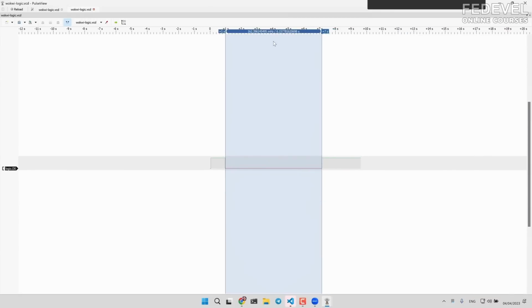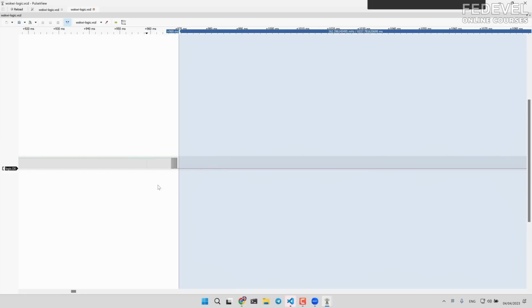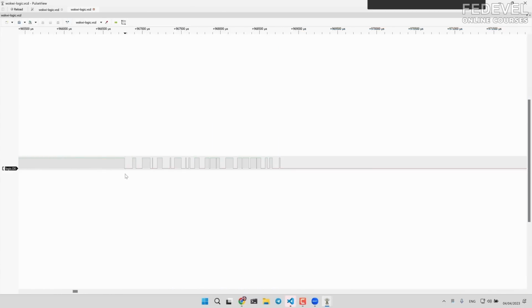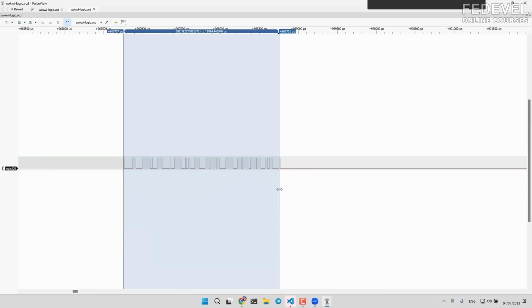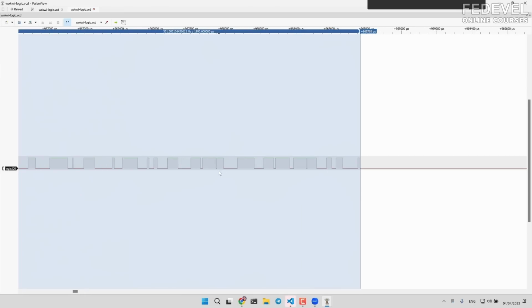it was pressed. It was pressed for 6.1 simulation seconds. But the interesting part is when you zoom in, you can actually see the simulated bouncing. We can see how long the bouncing took place, almost 2 milliseconds, and the actual pattern of the bouncing.